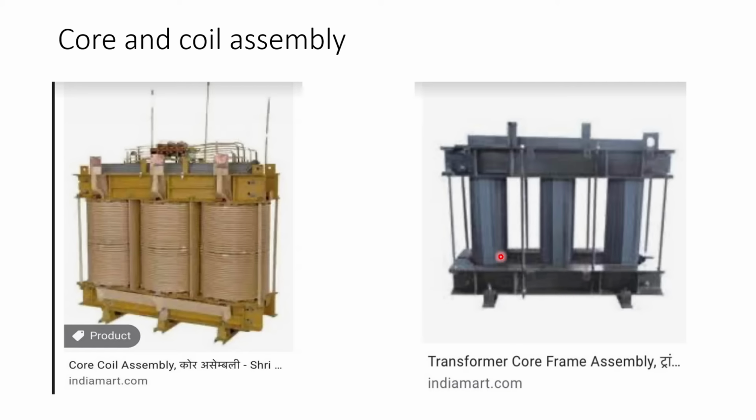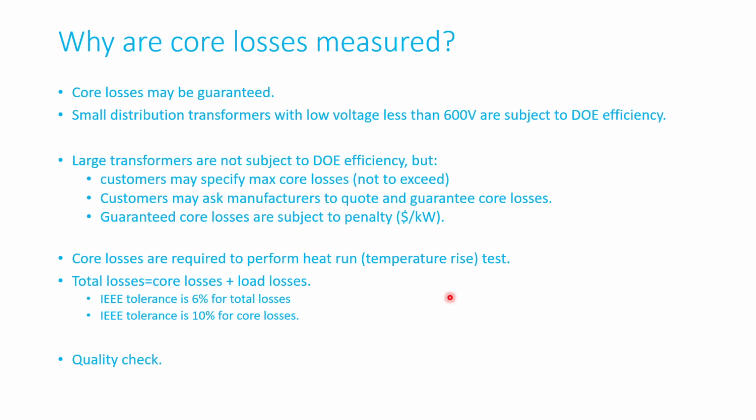So when you energize the transformer, the core is subject to the excitation current, which causes some losses. And also the winding that's energized causes some losses due to the I squared R effect, since the winding is made from copper or aluminum. Small transformers might have aluminum windings.